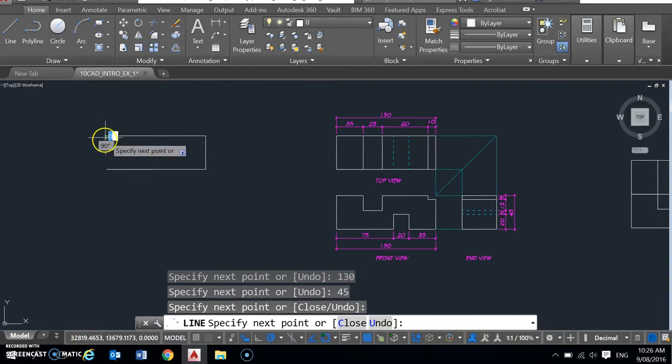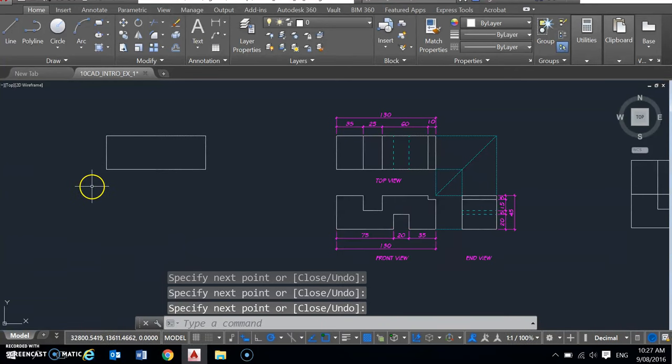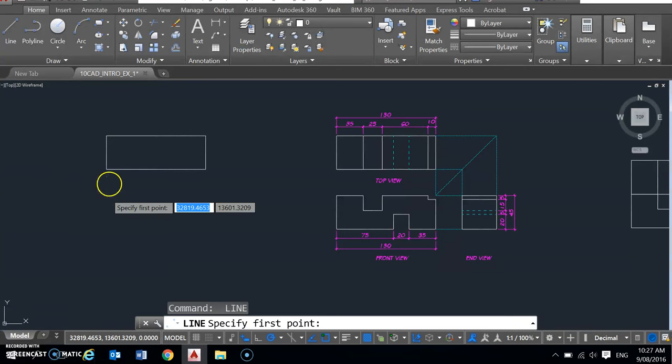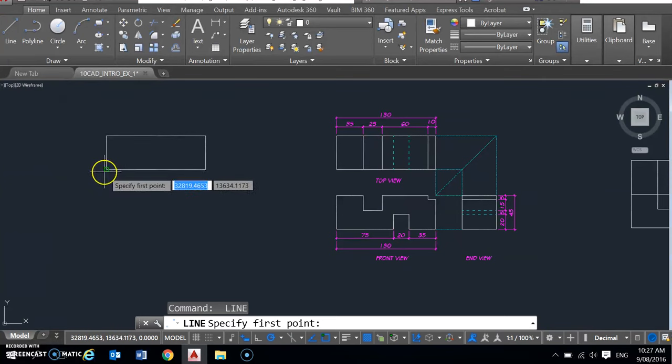So I'm just going to left click again and click on the end point and then press the space bar once because it's still attached. So that space bar is like the escape key. If I press the space bar again, it repeats the previous command, which is line. So I don't need to go back up to here. It's going to already repeat that command. So I could just go down here, but I actually want a 35mm space between these two objects.